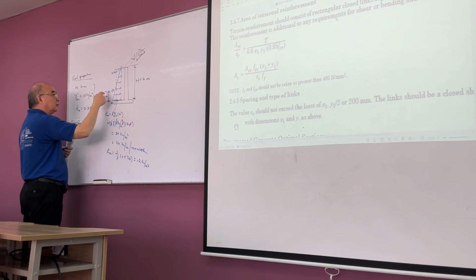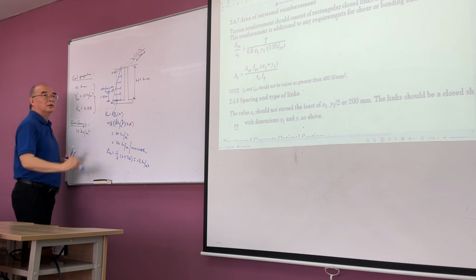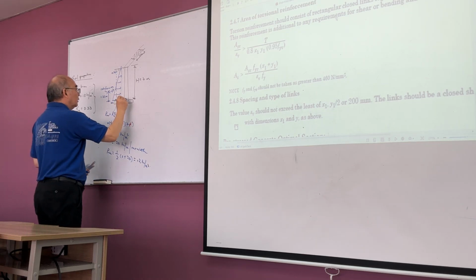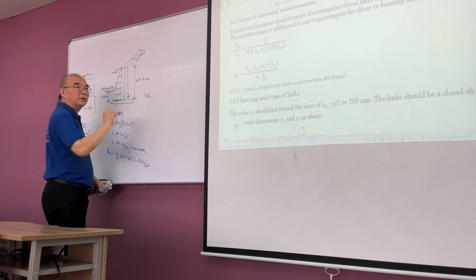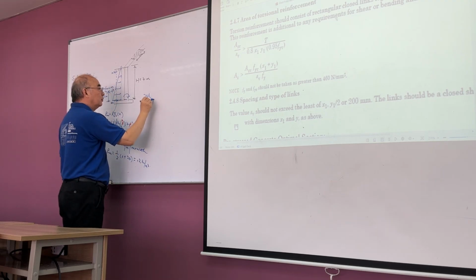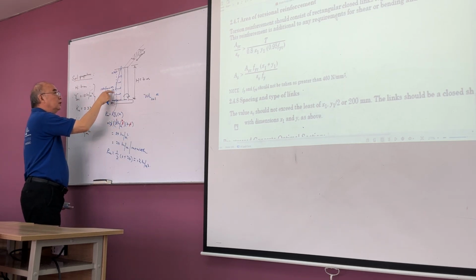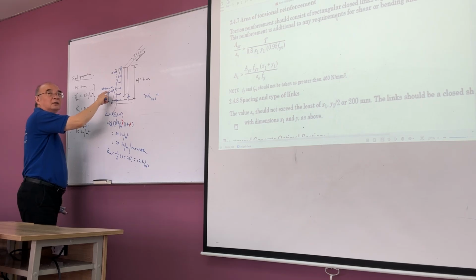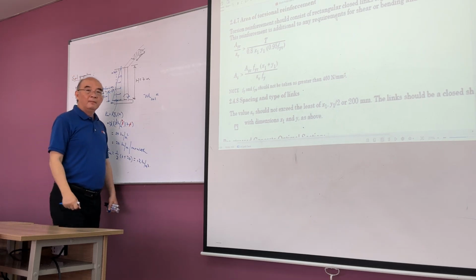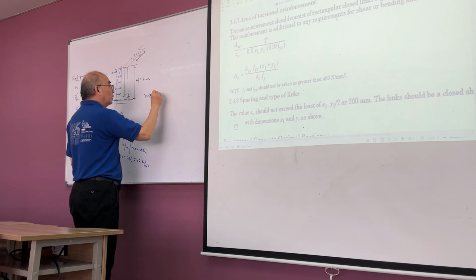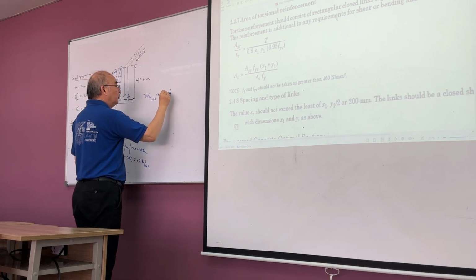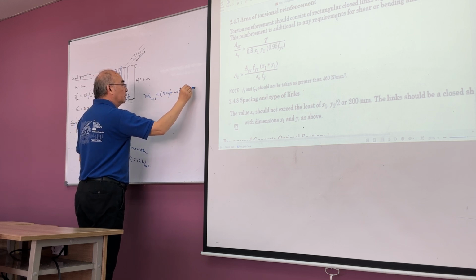So this total force, the average force, is 12 kilonewton per meter width. Then the moment, so you have this moment here, due to the soil, is equal to this force, 12 kilonewton per meter width, multiplied by 1.33 meter.